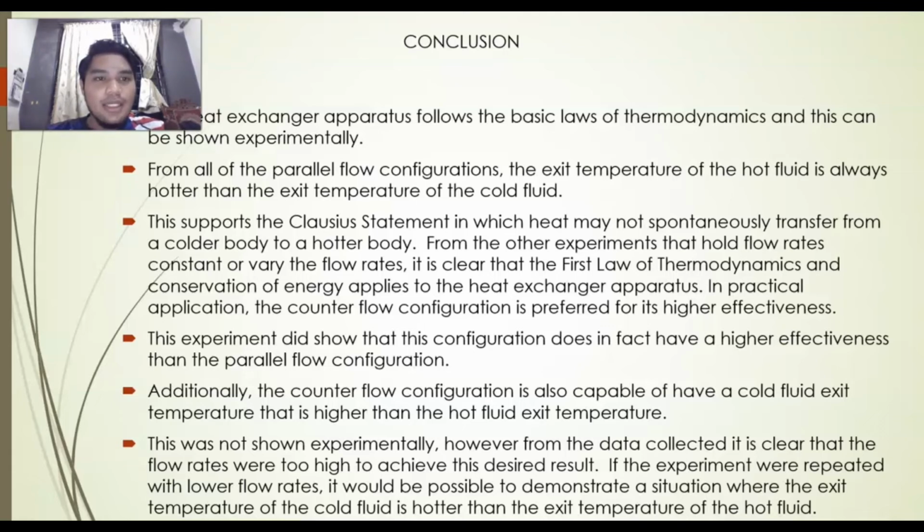For the conclusion, the heat exchanger apparatus follows the basic laws of thermodynamics, and this can be shown experimentally. From all of the parallel flow configuration, the exit temperature of the hot fluid is always hotter than the exit temperature of the cold fluid. This supports the Clausius statement, in which heat may not spontaneously transfer from a colder body to a hotter body. From the other experiments that hold flow rates constant or vary the flow rates, it is clear that the first law of thermodynamics and conservation of energy apply to the heat exchanger apparatus.